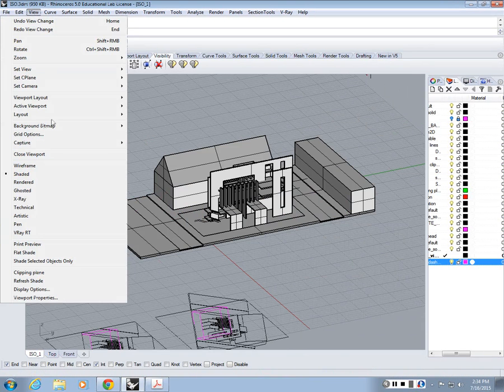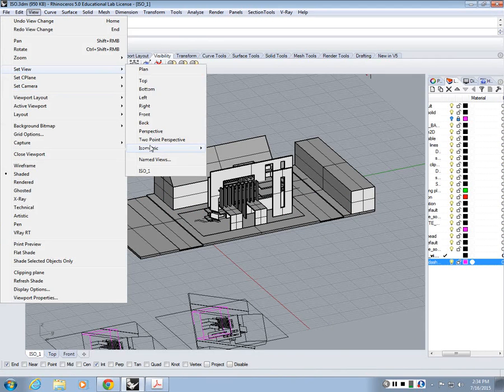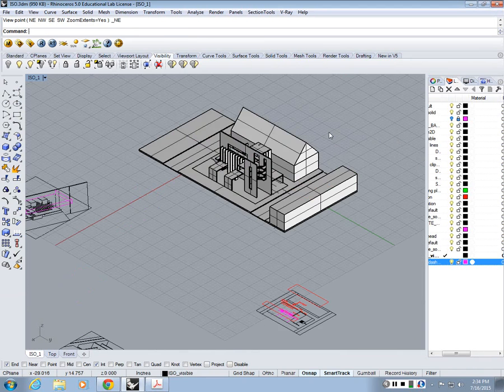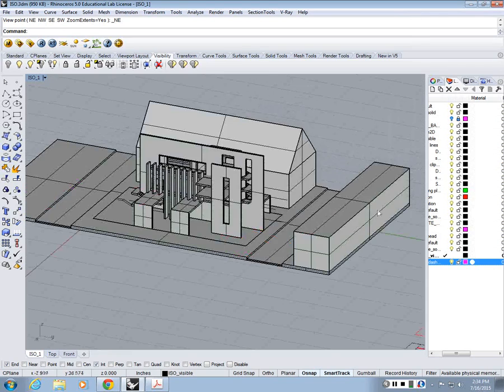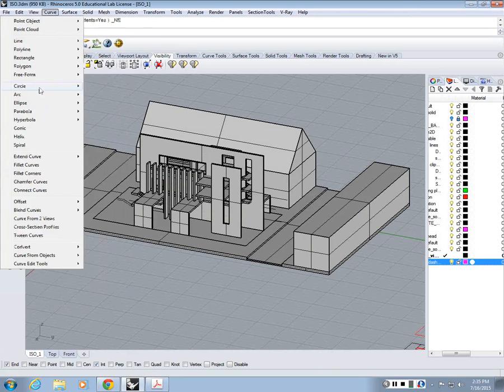So when you go to view, set view, isometric, any type of view you set up here, northeast, northwest, whatever, it's fit to the isometric angles. And when you do make 2D, it will be up to scale. But when we start tilting them, we are changing the angles, so we are losing the scale, right? So that's why I wasn't able to get the measurements. Tilting them how? Like tilting it this way or that way, because the projection is getting less and less. I understand, but were we doing that during the make 2D process? We did it actually. We kind of distorted it.